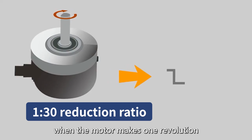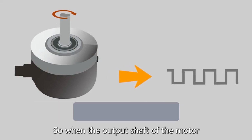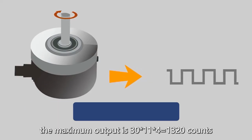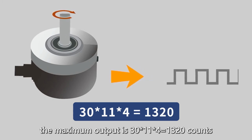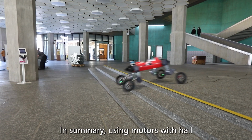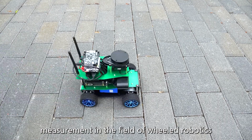When the motor makes 1 revolution, the single phase outputs 11 pulses. So when the output shaft of the motor rotates 1 revolution, the maximum output is 30*11*4 equals 1320 counts. In summary, using motors with Hall encoders is a common choice for velocity measurement in the field of wheeled robotics.